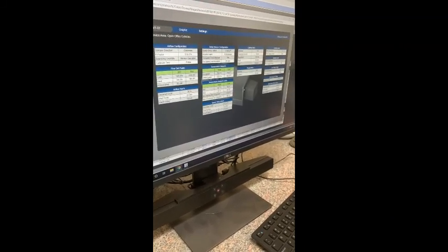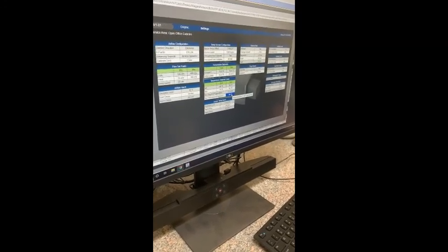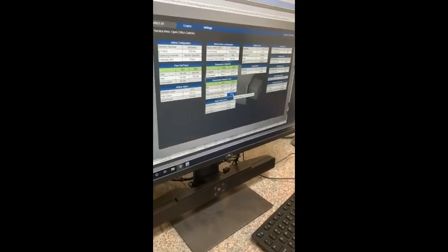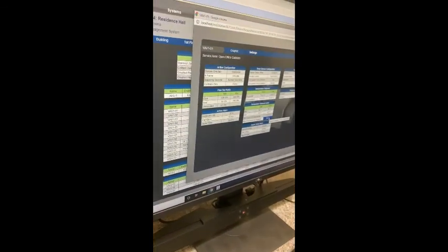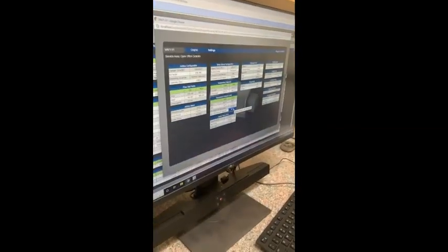And then from here is also the maximum discharge air set point. With VAVs, you don't ever want it to be too high, because a lot of the time the hot air will just stay up. So I would say maybe not go above 105 from my experience for downdraft VAVs with reheat. Some of those zones that are cold, maybe the discharge temp needs to be raised a little bit.